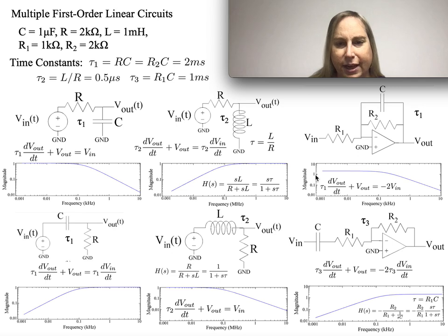And notice that at low frequencies, this is now much bigger than 2, or much bigger than 1. It's now at 2. The gain is actually minus 2. It's actually minus over here, but I'm just looking at magnitude, so you're not going to see the sign here. But notice by putting the capacitor in the feedback loop here, it actually gives me an interesting response where it's high, basically it's 2, and then it falls off. It gives you something that looks exactly like the classic differential equation we had here, except that my input is now minus 2Vn. Everything else looks basically the same.